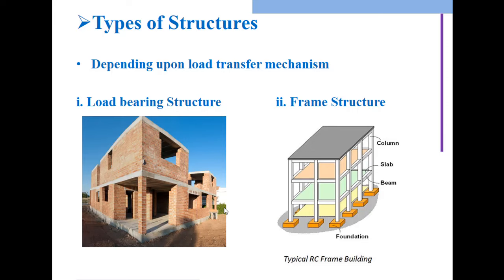So as we were here, you can see the different elements, right? These different elements may consume different kinds of loadings. So on my website I already gave you the dead load calculations of the beam and column. So ETABS works on the phenomenon that if you assign the self weight, even in STAAD.Pro also, if you assign the self weight for the overall building, what does it mean?